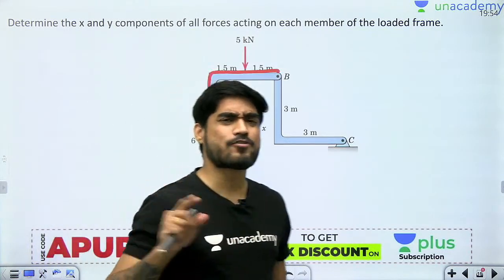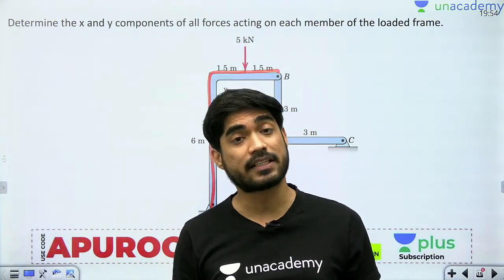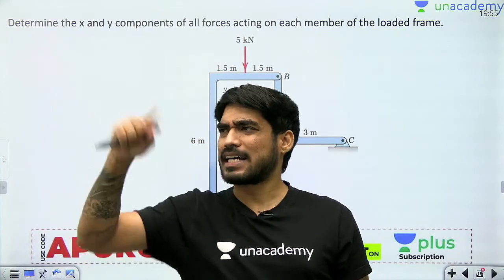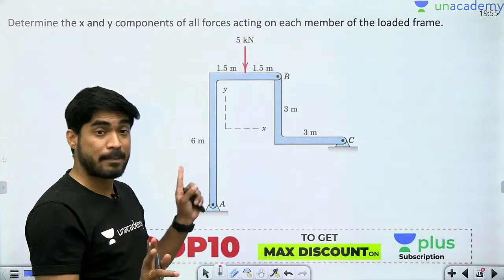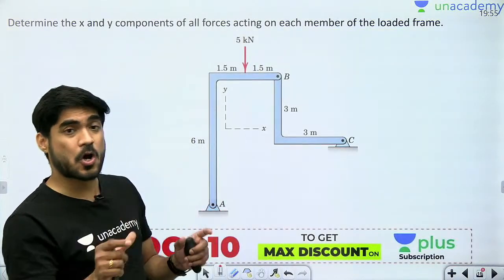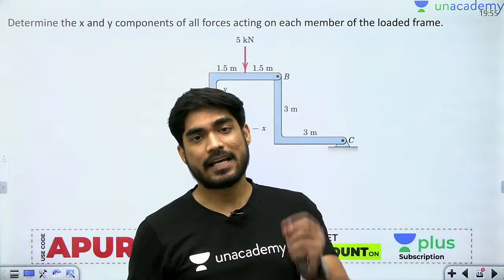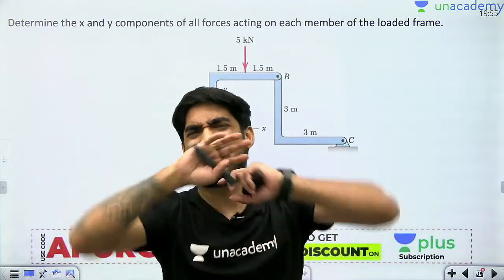हम वहां पे मेथड ऑफ जॉइंट में मेंबर्स का एफबीडी नहीं ड्रॉ करते थे, हम किसका एफबीडी ड्रॉ करते थे? We used to draw the FBD of joints, joints को अलग करके एफबीडी ड्रॉ करते थे। यहां पे we are going to isolate the members and we are going to draw the free body diagram of each member. Is this clear to everyone? It is not necessary to draw the FBD of every member.